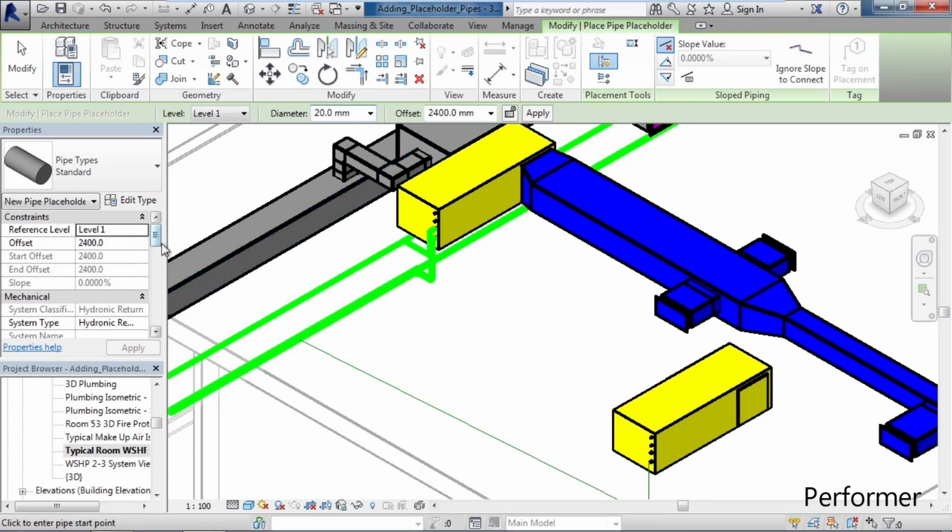And you have all the other information as well, minus a few things, but all the other information that you would see within a normal pipe if you created it. Things you don't see are, again, the actual alignment tools for horizontal and vertical, and the ability to add insulation and lining to the actual pipe. Once you're done selecting or drawing a pipeline segment, click Modify.